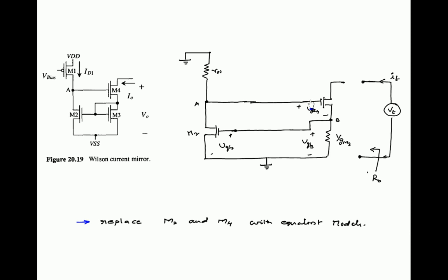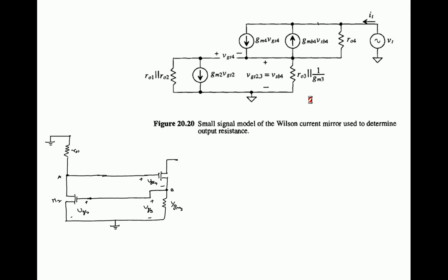Generally, body effect increases the threshold voltage. So if we consider the body effect, for the given VGS you will get less current compared to the case without body effect. So the effective drain current reduces when body effect is considered. That is modeled with an arrow opposite to the actual drain current direction.